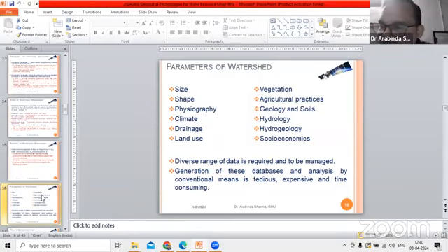of the hydrological cycle, but all soils don't have the same hydraulic conductivity and so on, right? Or their porosity is not the same. If porosity is more, water will percolate and infiltrate to recharge your groundwater. But if the soil is like clay soil, having very less amount of porosity, in that situation, what will happen? A very small amount of rainfall can produce runoff and ultimately cause flood. So that is why we have to understand everything, geology and soil.